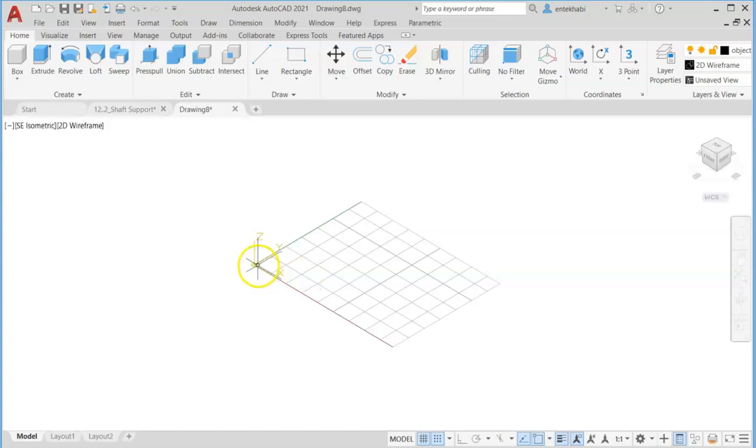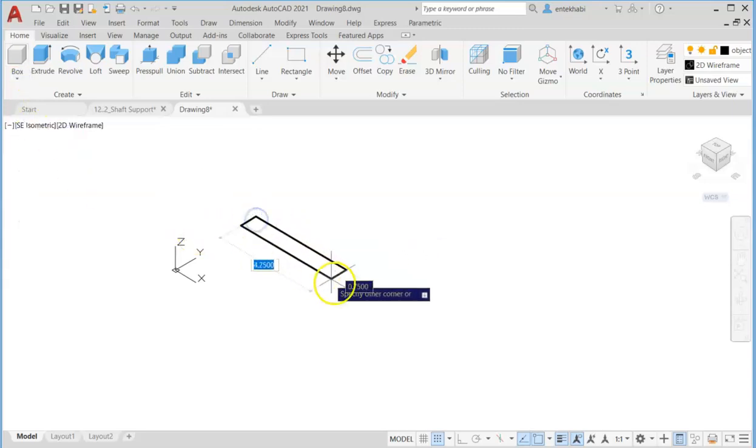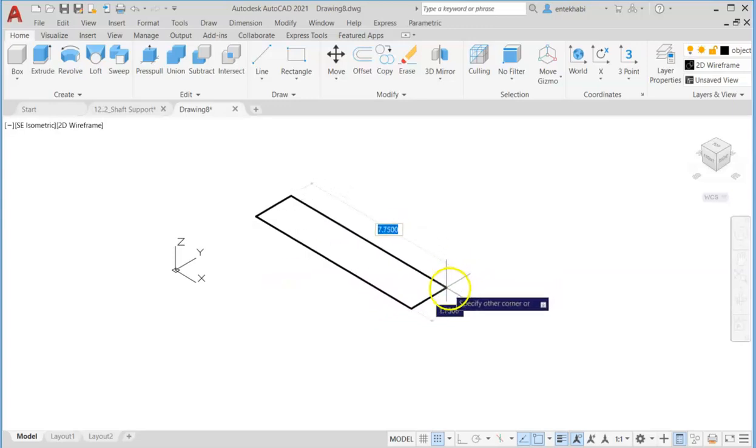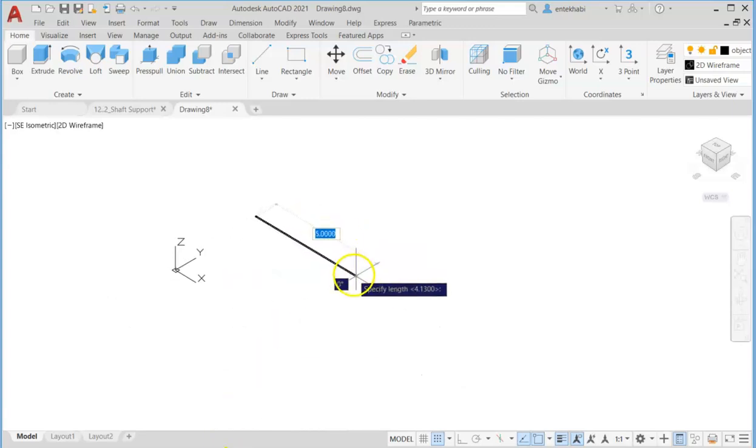You may want to turn the grid off by pressing F7. Now my UCS is parallel to the floor, which is default UCS, what we call world UCS. On this UCS, we will create the box. Create a box, selecting a point, having the length selection from the sub command. Press F8 to turn ortho on and set your line direction parallel to x-axis.